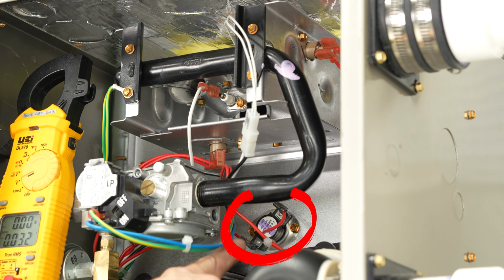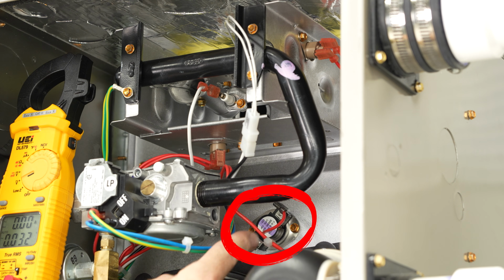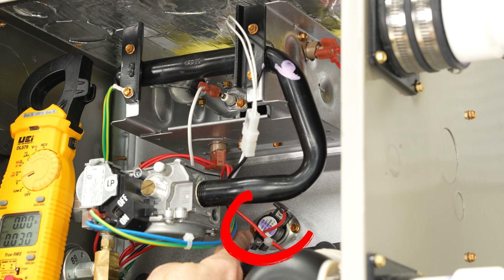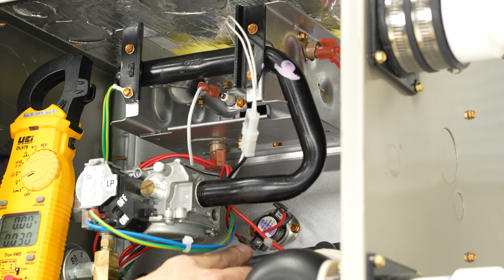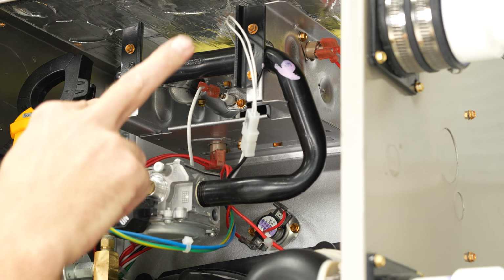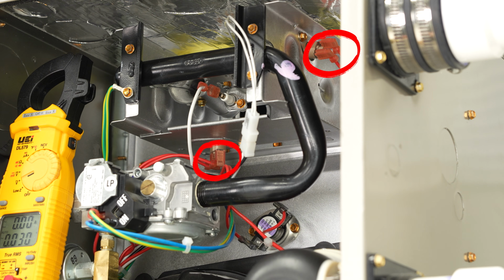Now this thermal limit switch back here could trip due to something simple, such as maybe a filter is not changed and the filter is completely dirty and clogged shut, so there's no airflow across the heat exchanger area. Or maybe a flex duct in the return has collapsed on itself. So it could be a simple reason why these are tripping, but the flame rollout switches are typically a more complicated or more dangerous situation. Caution should be taken either way.